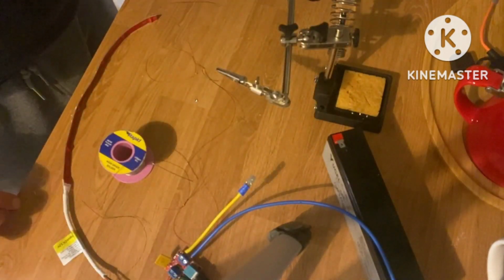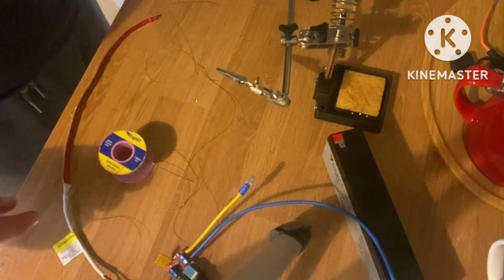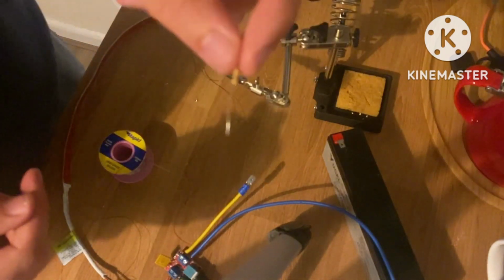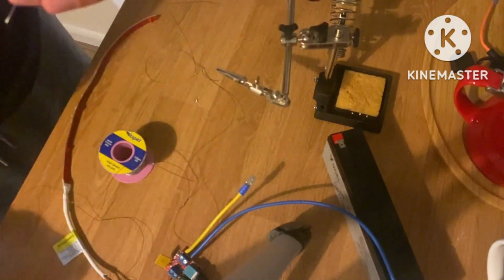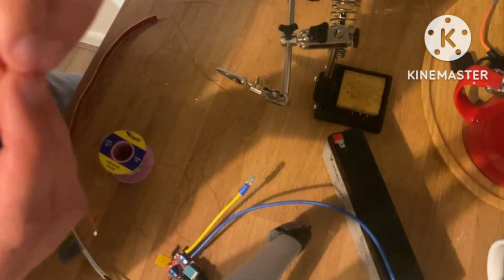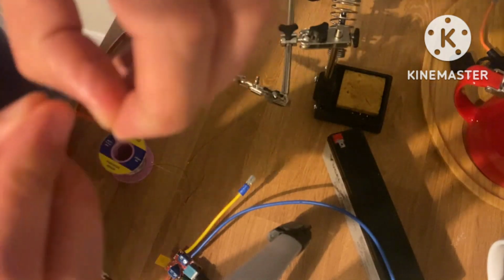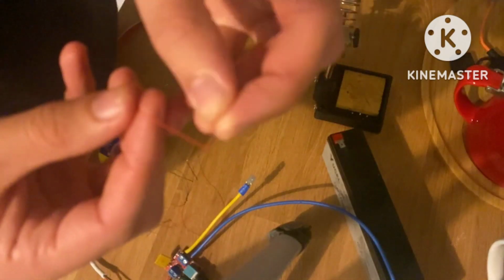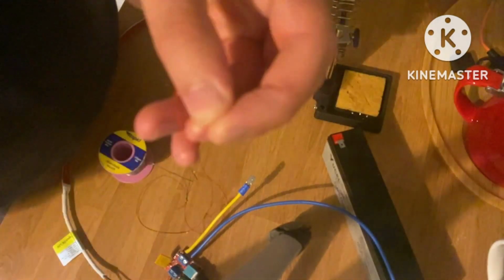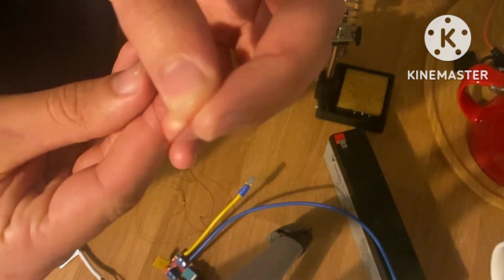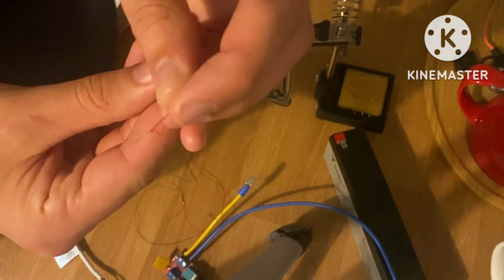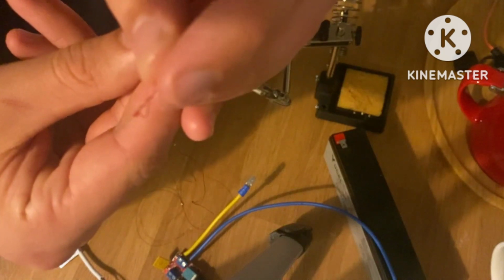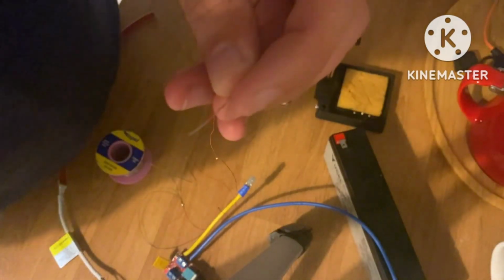The last thing that we need to do before we can connect any power is we need to put what's called a protection resistor in the path. What this does is it just regulates the amount of current that goes through the LEDs, which is of course a good thing. What I tend to do is I just roll some of the LED wire around the leg of the LED as such. There you go. We'll just solder this in place now.